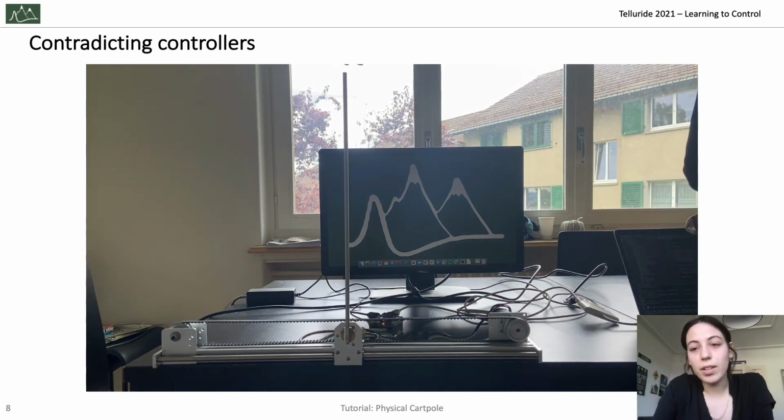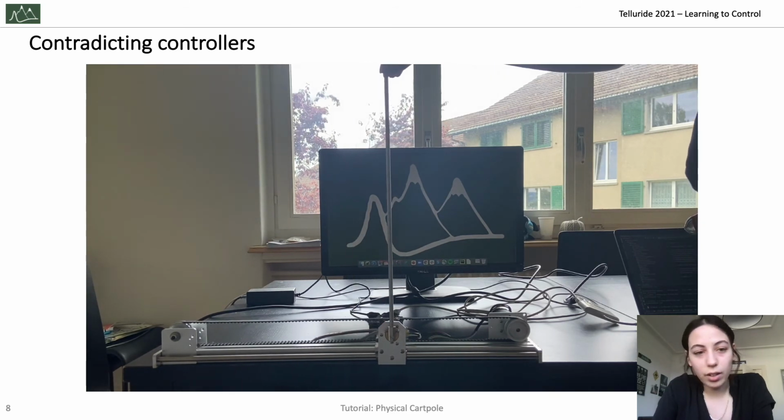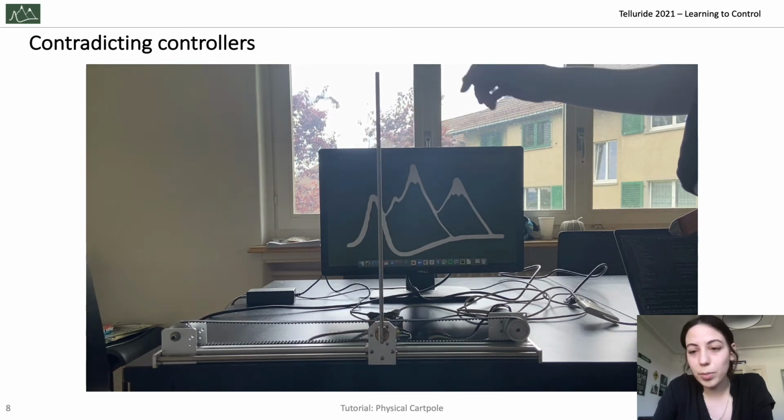This is why a trivial implementation of a PID controller won't work here. Before moving on to how a PID controller works, I want to point out how we measure the states of the system. There are 2 sensors. One of them is for encoding the speed of the cart by counting the turns of the motor. This is where the motor is located, and the motion of the cart is achieved by the motor turning the track belt. And the second sensor is for encoding the angle position.